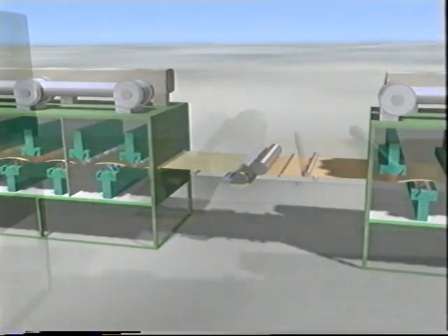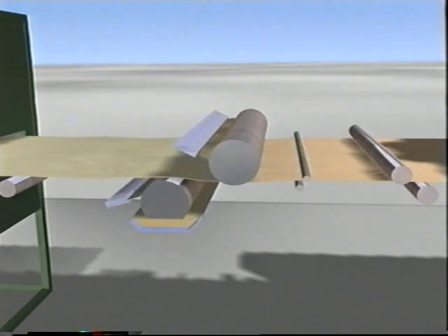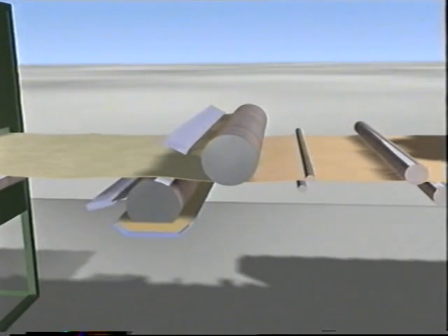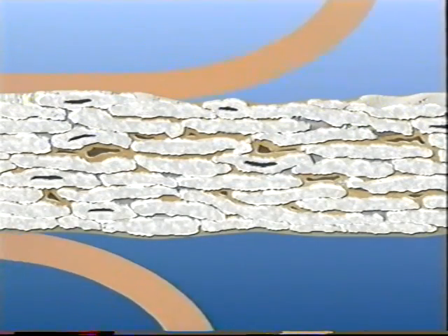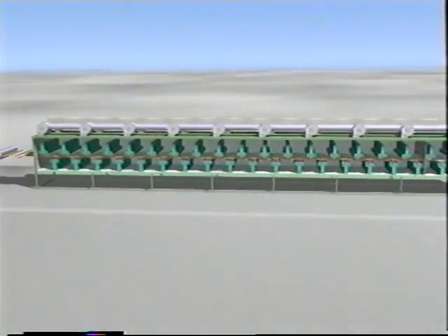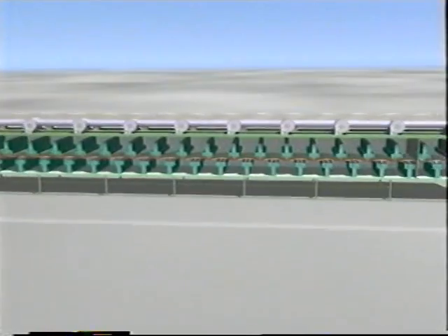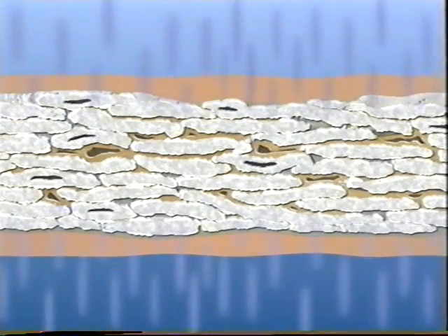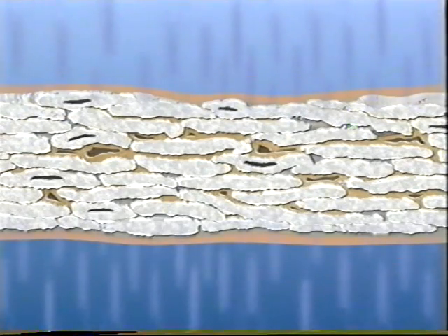After the web has cooled, gravure rollers apply melamine resin to both sides of the paper. At the interface, blending of the two resins takes place. During the second drying phase, the paper is also guided through the oven on a cushion of hot air. As this occurs, the melamine coating loses water until it contains about the same moisture level as is found in the impregnate's core. At the same time, the thickness of the melamine layer is also reduced considerably.